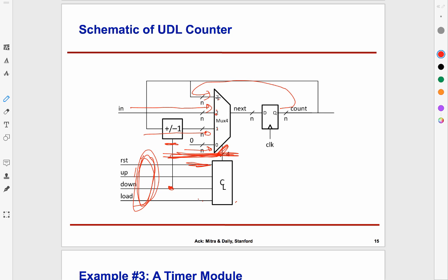So our job now, in our original circuits, we were designing the entire combinational logic. Here, by parceling out this multiplexer and adder and all, we have a simpler combinational logic task remaining, just the controls for these multiplexers and arithmetic units, and usually you can just stare at the logic and write down the equations. Typically it tends to be straightforward.